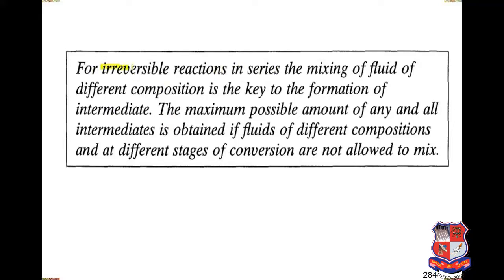For all the reactions in series, the mixing of fluid of different composition is the key to the formation of the intermediate. The maximum possible amount of any and all intermediates is obtained if fluids of different compositions, at different stages of conversion, are not allowed to mix.